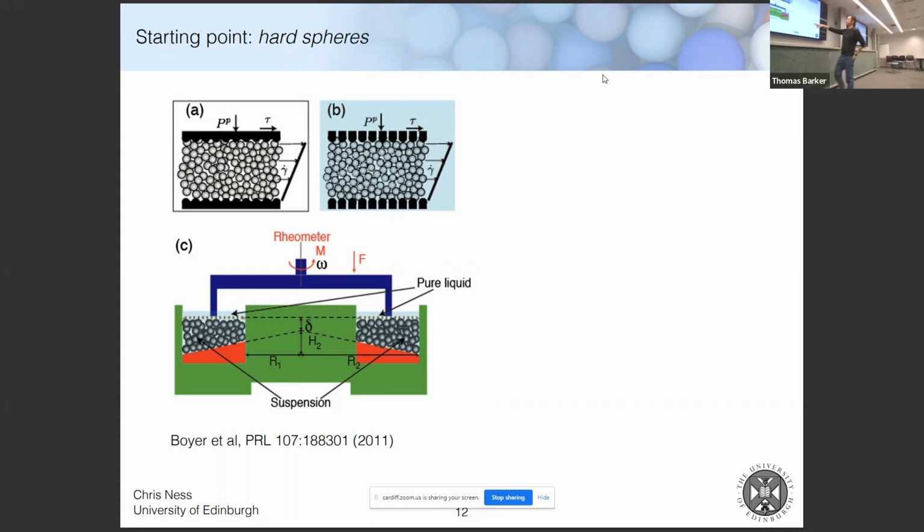And so this device has particles in here, which I think are hundreds of microns to millimeters in size. And they put the particles in a ring, and then they shear the top of the ring. So they're applying a shear flow. And the important thing is that there's a grid here which allows the fluid in and out, so the system can dilate or compress depending on the stress that you're applying, which means its volume fraction is allowed to change.